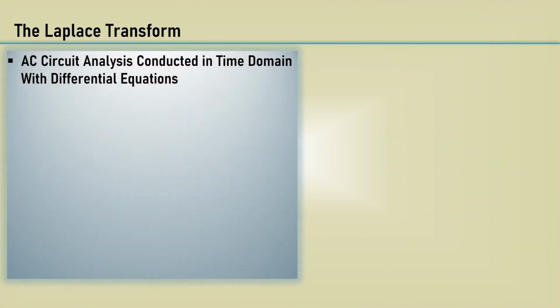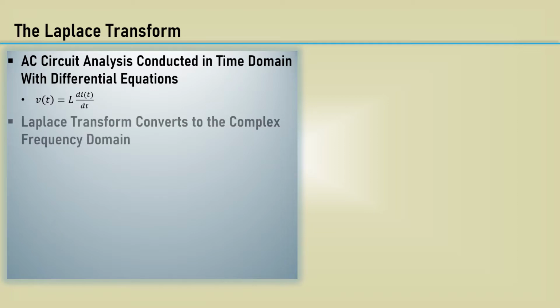The Laplace transform is one of the most fundamental and useful techniques for circuit analysis. AC circuit analysis can be conducted in the time domain with differential equations, which can be difficult to work with. The Laplace transform converts the differential equation to the complex frequency domain, which can be solved with simple algebraic expressions.